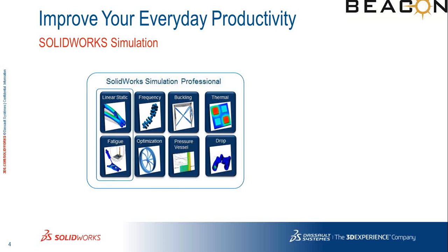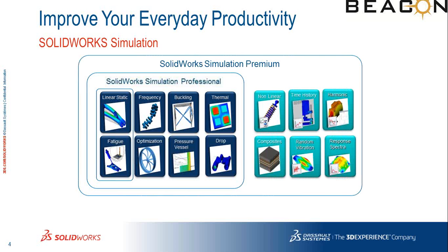Like I mentioned previously, we can do time based in simulation standard, and event based is included in simulation professional. Other than this, we have something called simulation premium, which deals with non-linearities. If you're working with non-linear materials like rubbers or plastics, the non-linearity doesn't have to be only the material, but might be loads as well, like load varying with respect to time, or non-linear contacts. All kinds of analysis can be done in non-linear analysis.